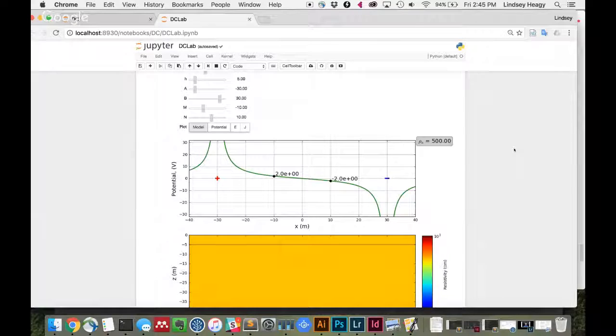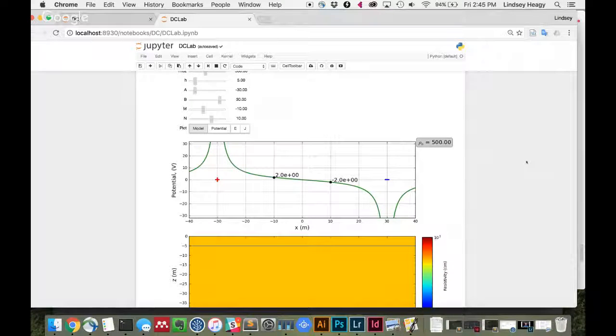And so in between, the electric potential goes as this kind of signature. Good. Now I could go ahead and measure that, right? Because if I take a voltmeter, just the same one you use for measuring the voltage of your battery, and you just plugged it into the ground at 2 locations, you'd measure a voltage difference.